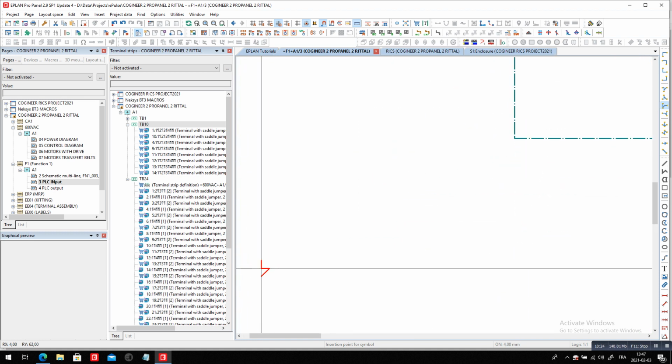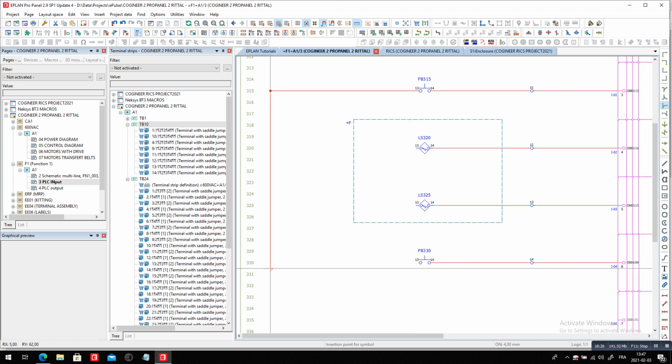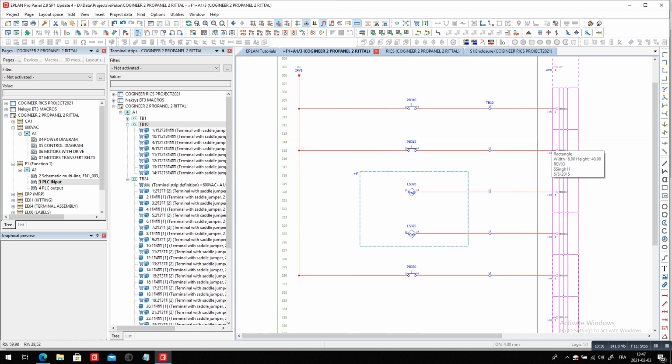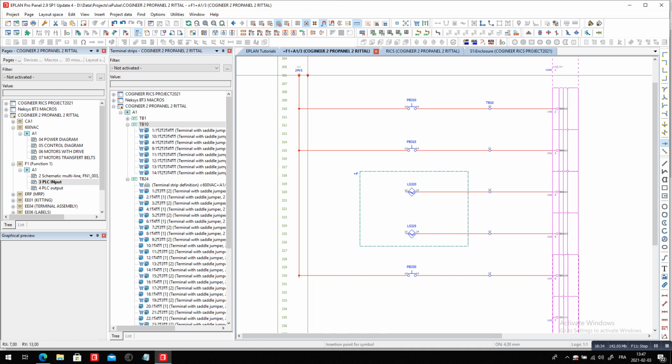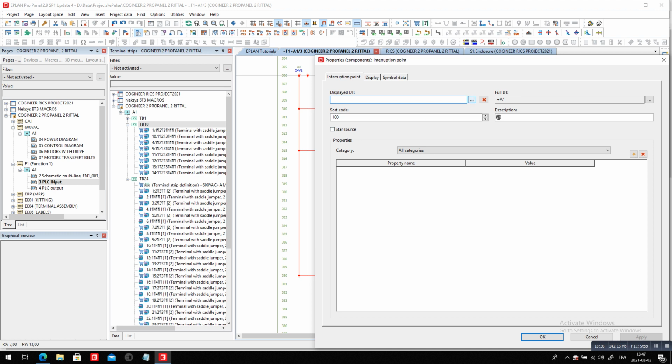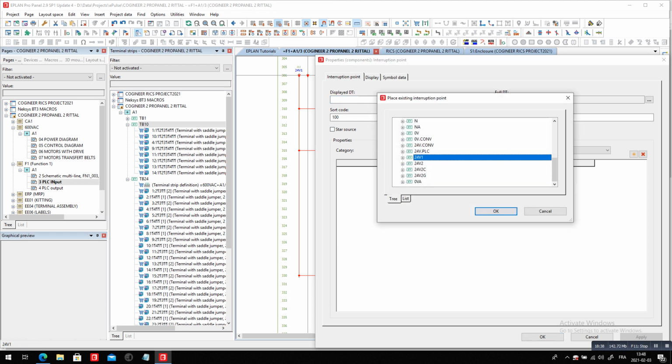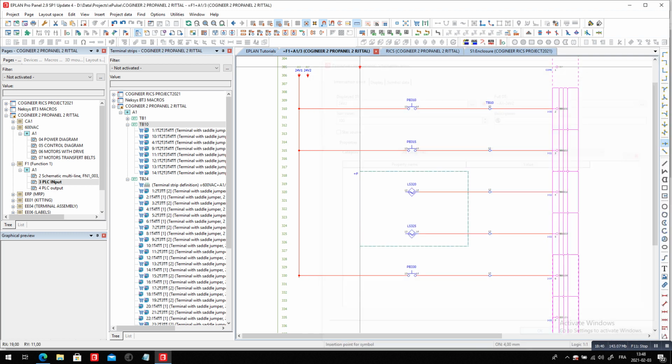This is all cool. Now, for the field elements, I prefer actually using the second breaker. So that is my 24V2. So far, so good. You are actually protecting the field devices separately from the regular terminals.